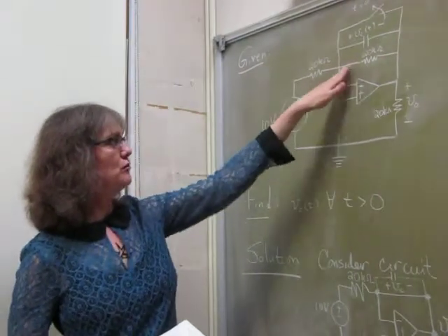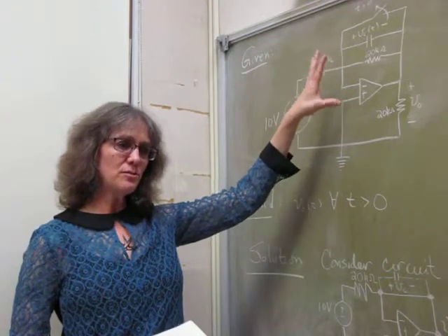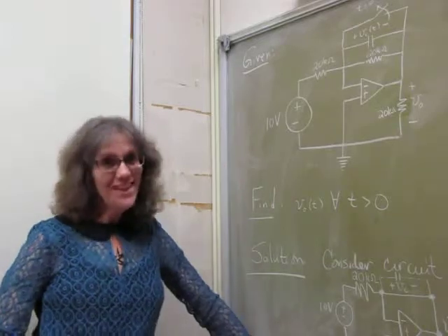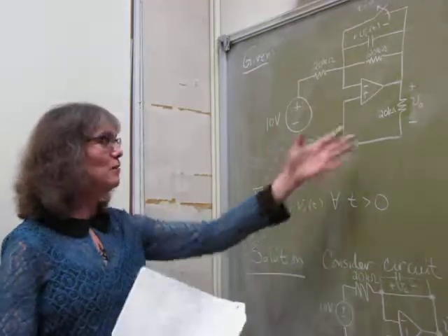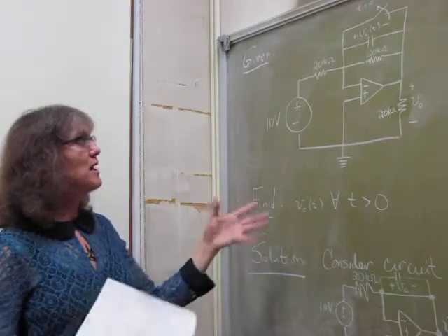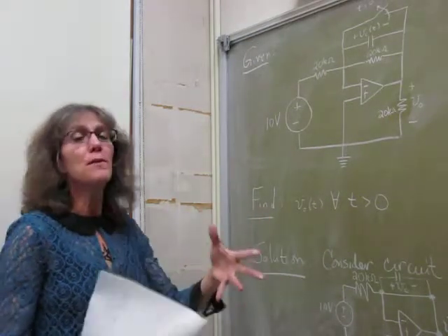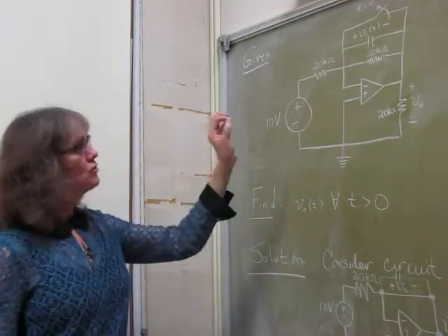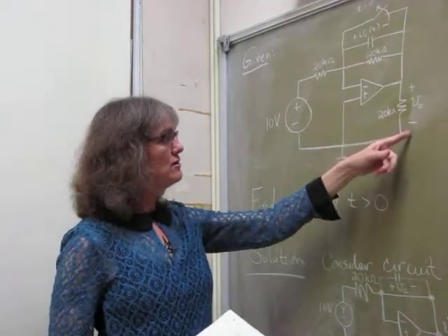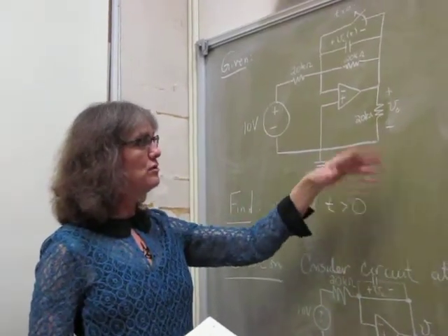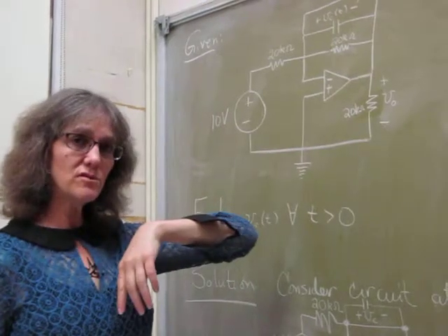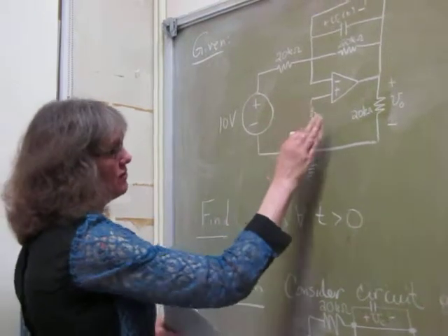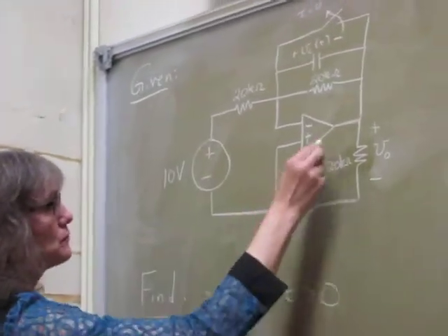Okay, let me just talk for a sec about op-amps in general. I know that sometimes students feel intimidated by these things, but just don't. They're only models, like everything. A resistor is a model, capacitors too, they're mathematical models of what happens in the real elements in a circuit. For instance, the model for the resistor is that the voltage across the resistor is always equal to the current times the resistance of the resistor. And we know that the directions are important. But for the case of the op-amp, here's the model.